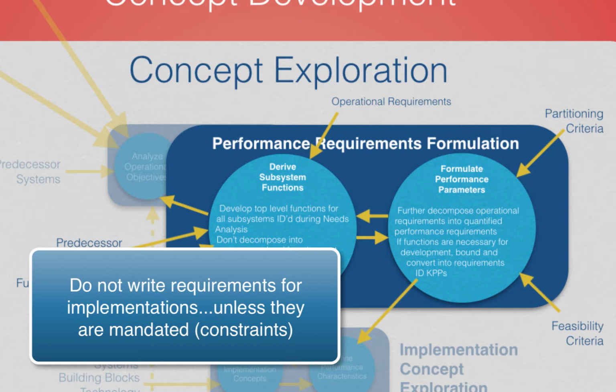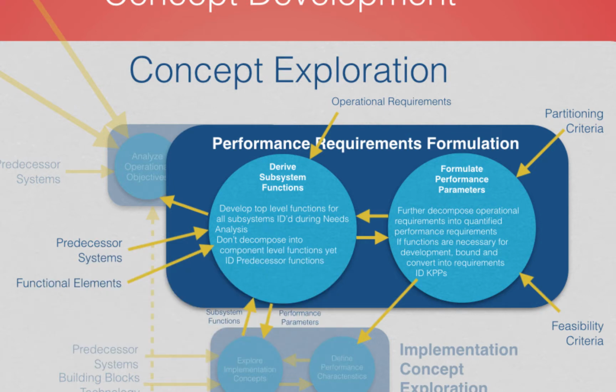For my gas pump project, it's easier for my system to operate on the pre-existing gas pump islands, those concrete islands at gas stations, than it is to require a gas station owner to build a unique facility to accommodate my system. Therefore, my system must adapt to these gas station islands to include mounting provisions, the physical footprint, interface with the underground gas tanks, and interface with the network and power provided by these gas stations. On top of complying with industry standards such as UL 87, I discovered these during my concept of operations development.